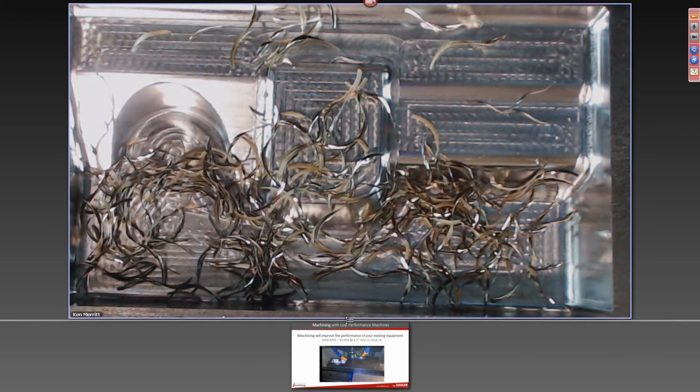And I mean micrometer style, within tenths, okay? And of course, that's going to depend on how fast your machine can respond to the feed rate changes. But on a good machine with a good response time, you're going to see chips throughout the entire cut that are within a tenth or two of each other, okay? Very, very stable chip thickness. What that does for you is that keeps a continuous and a very constant load on the tool.